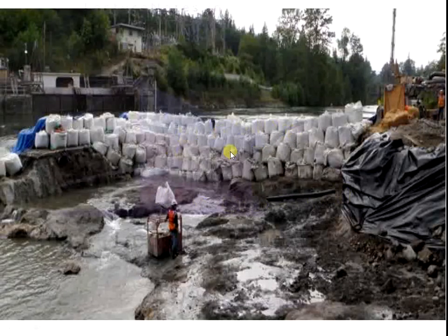This type of sandbag fill cofferdam is easily constructed, but it is applicable only when the water depth is less. Here we see the bags laid one by one on the uneven bottom surface.